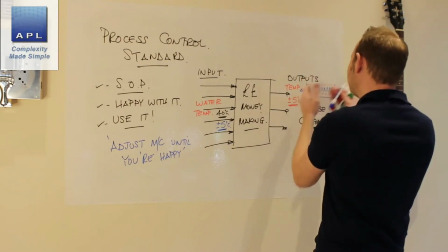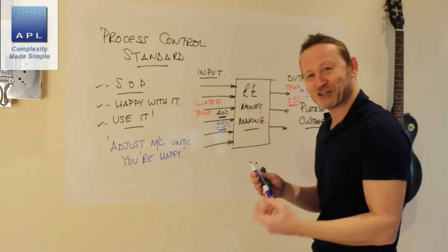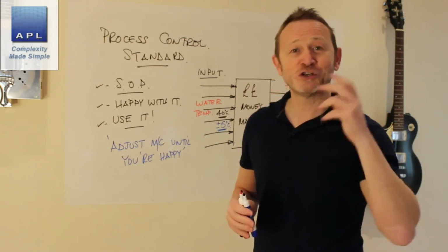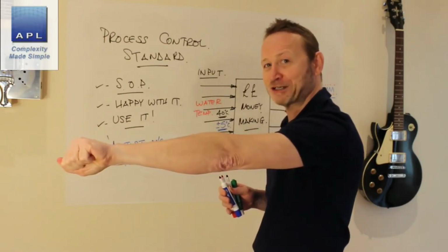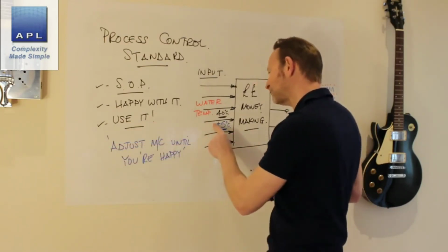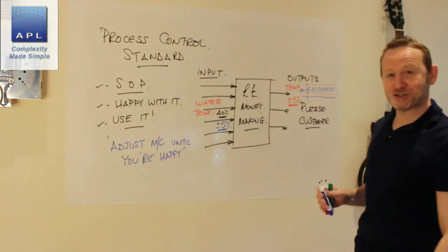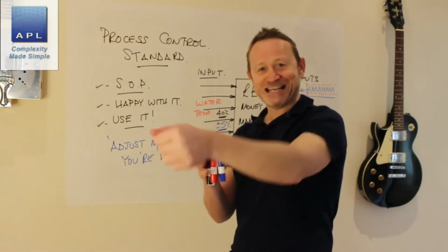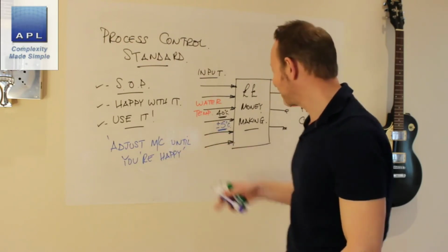Now, you gave the plus or minus 5 degrees to the machinery and its ability to control, because it can't keep the thing perfectly in place. You've taken the plus or minus 5 and you've given it to a dial that was perfectly stable. Now what does the operator do? Well, the operator notices the process going up and down, and what does he do? He now dials in plus or minus 5 degrees this end.